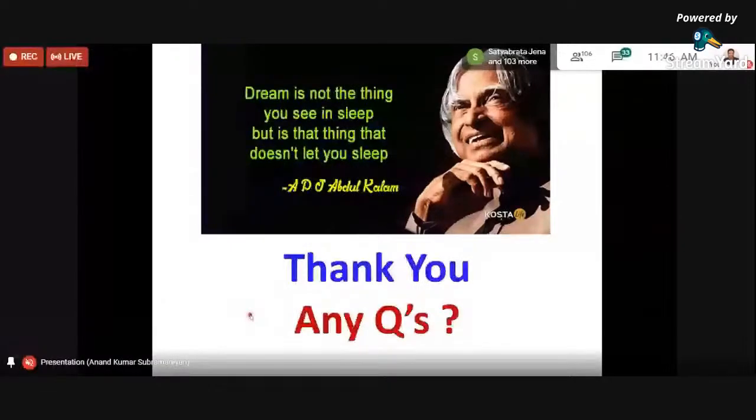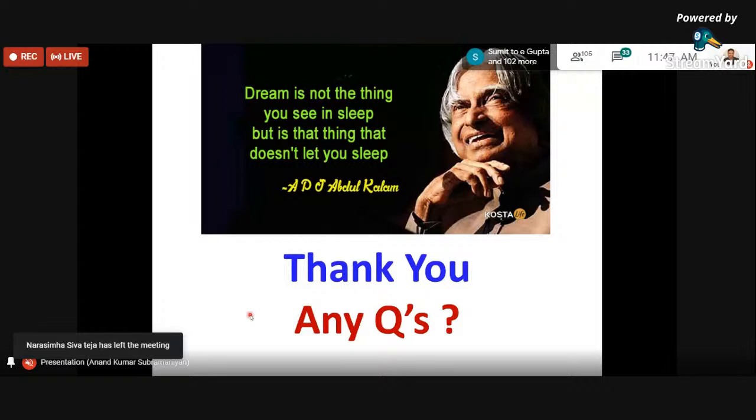My presentation was from the viewpoint of the grain size, right? For example, from theory, we know that if your material is ductile or tougher, if you look at the microstructure, the grain size will be bigger, right? That's why, as in the materials engineering course, there are several strengthening mechanisms. One of them is the grain size strengthening mechanism, where we try to reduce the grain size, and then from the Hall-Petch relationship, we say that the material has become harder.